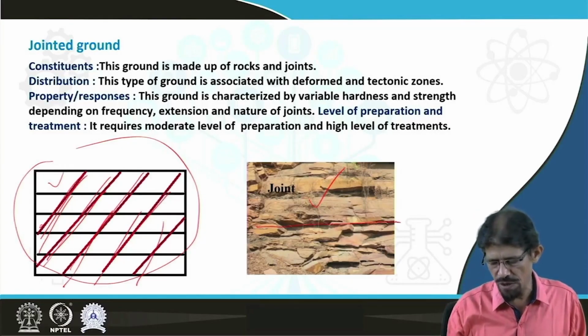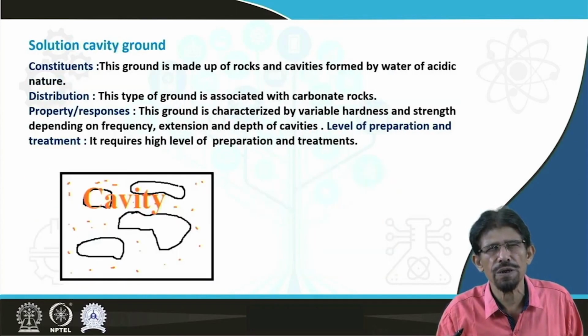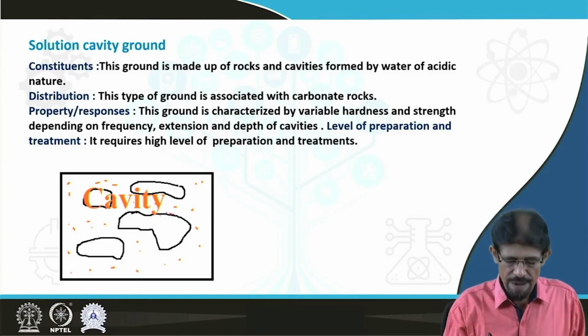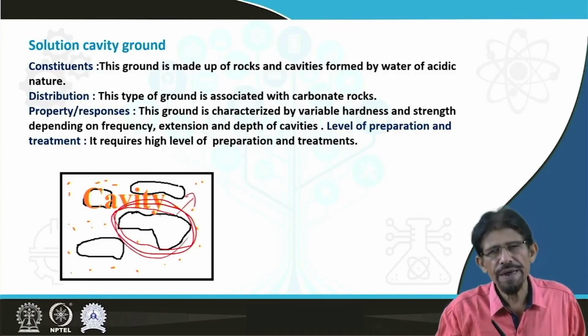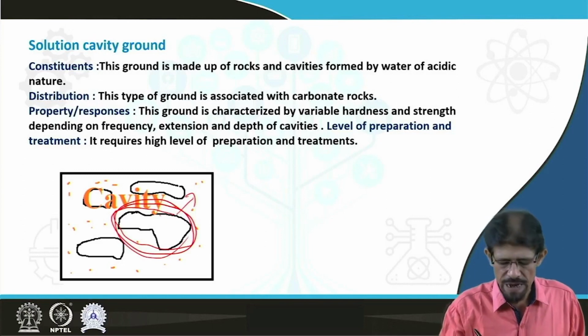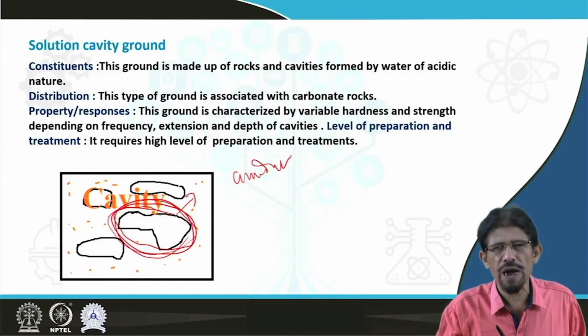Here we are going to see this type of ground, bedded ground, and some transverse ground also from the Vindhyans, from the Sonbhadra area. Solution cavity ground is a very peculiar type of ground and creates a lot of complications in assessment of strength, hardness or durability, because the dimension of this solution cavity is going to enhance with respect to time depending on availability of acidic water and the suitable surrounding conditions.